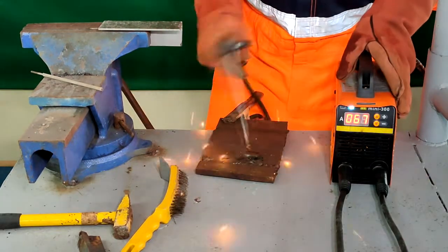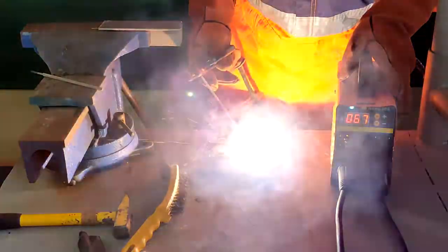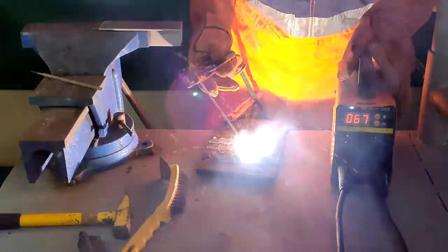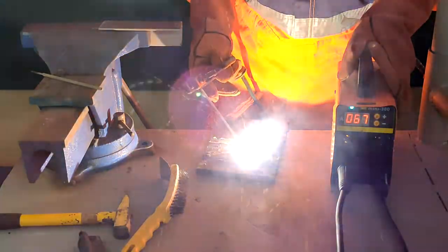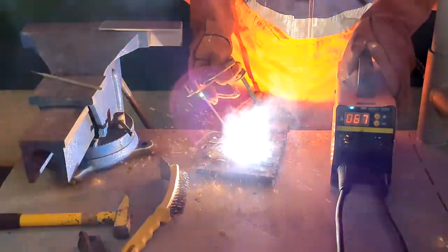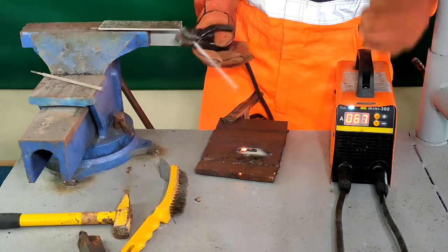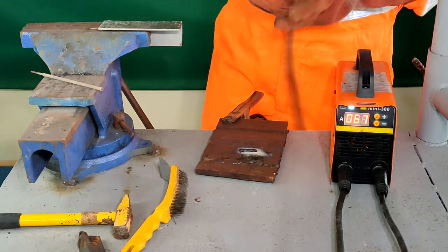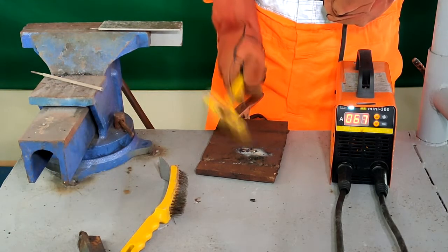Remember, conditions may change. For example, if you are welding multiple passes in a vertical position and using a weave technique, you may need to increase the amperage when weaving over a prior weld bead. You may want to use a higher setting for welding flat and horizontal than for welding in other positions. One welder may prefer to use a slightly higher setting and travel faster than you, so set the amperage for your technique.